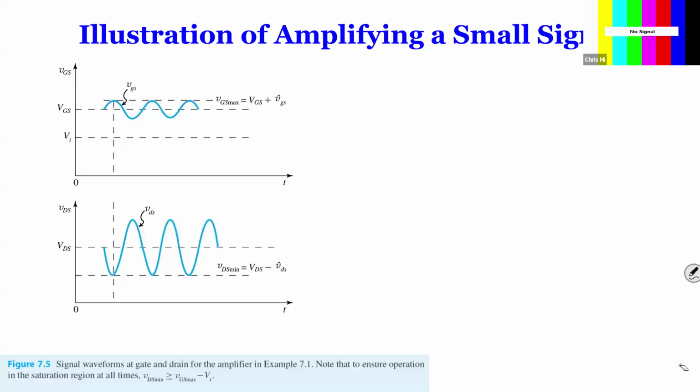So in real life, when you build the circuit, what you do is you add a capacitor. If it's big enough, you guys remember the impedance of a capacitor is 1 over omega C, right? So if omega is big enough and C is big enough, 1 over omega C is close to 0. So that's basically how you can get your AC. But for DC, that's an open circuit, right? So that's how you get it.